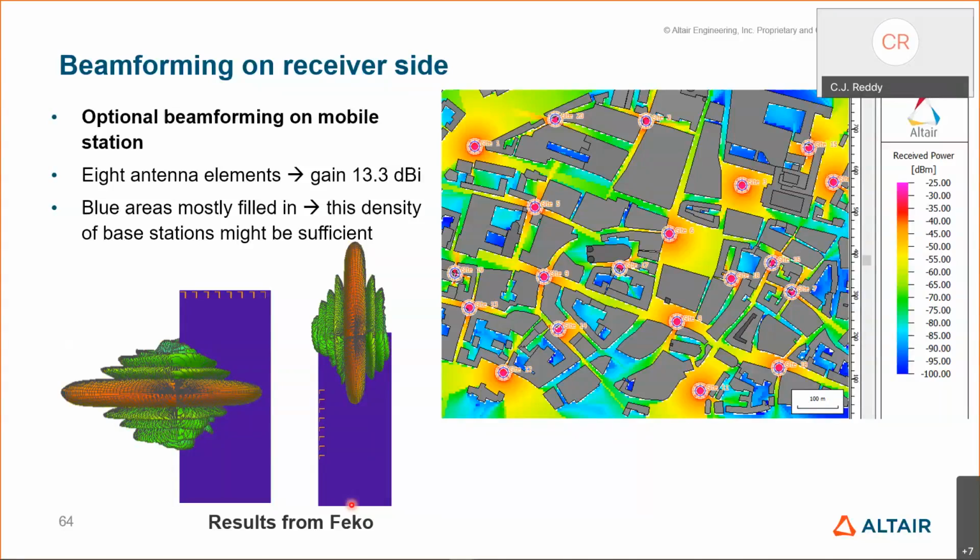What characteristic mode analysis will do is, if you take that arbitrarily shaped structure with a conductor or something like that, it tells you what kind of modes that shape can support. Here we're not talking about cavity modes and things like that. We're talking about an open radiating structure and its modes. Characteristic mode analysis, through the Method of Moments impedance matrix, can give you the different modes that particular structure can support. Here also, we're not talking about a structure with an excitation. This is a structure with no excitation; the naturally supported electromagnetic modes can be found.